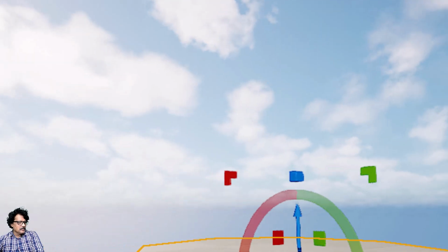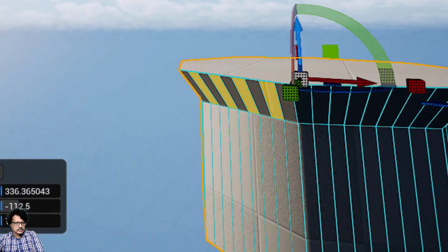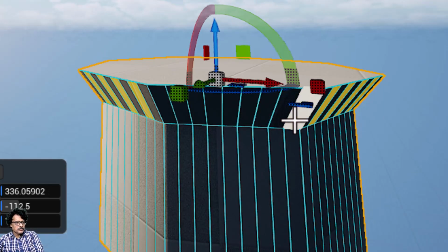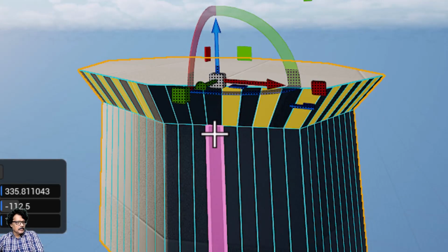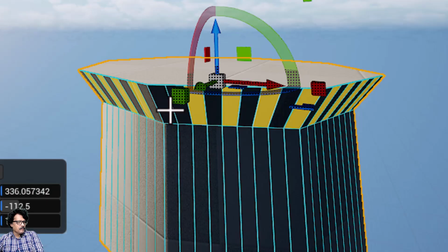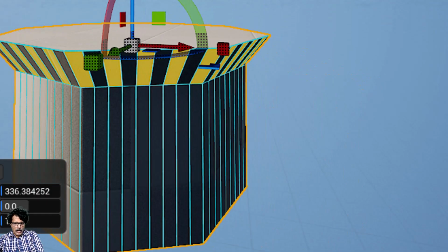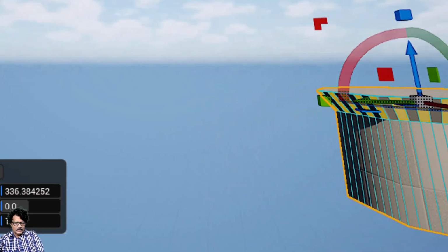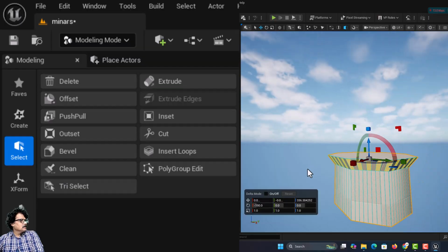I will just turn around here, and this is the last face selection, wherein I select with Shift pressed 1, 2, 3, 4 and 5 faces. So, now I have selected all the alternate faces here.